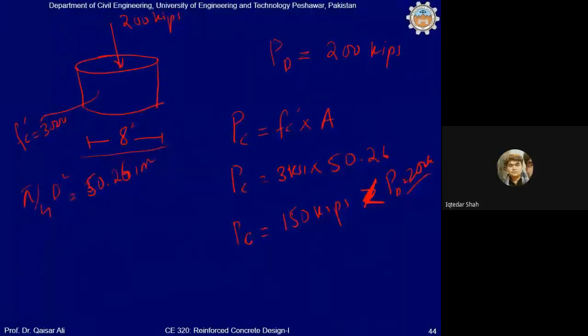How to improve the capacity? सर एरिया को ज्यादा करेंगे। दूसरा ऑप्शन क्या है? सर मटेरियल की स्ट्रेंथ बढ़ा दें। It is the combination of strength of material and area. तो या तो आप स्ट्रेंथ को इंप्रूव करें या आप एरिया को इंक्रीज करें। क्लियर? अच्छा, अब for example the material properties are fixed, you cannot increase the material strength, so the only option is that you have to increase the area of the member.